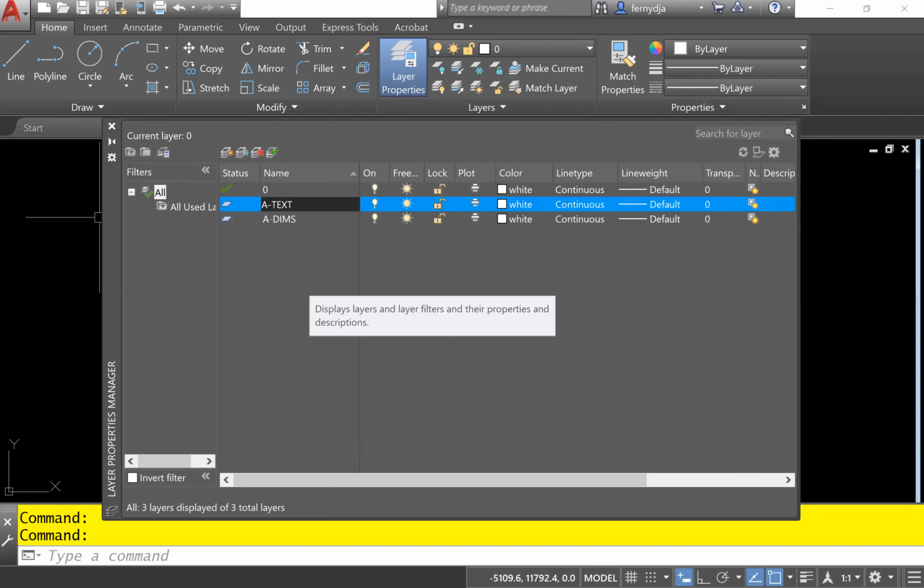and then you press comma again, A dash DOOR dash TIMBER, for timber doors. Then I'm going to press comma again. Then it's A dash WIN for window, dash GLAZ. Glaze is the category for that. So that's my window layer. Then I'm going to press comma again.